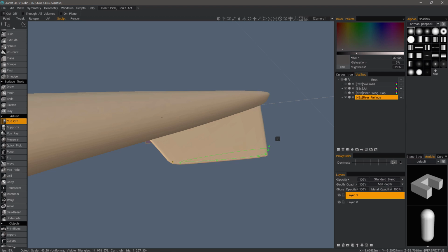And as you may know, you have different point types when using this curve. You have a standard spline that has curvature that runs through the point, and then you have a B-spline, which is quite a bit smoother because you can see it's weighted based on the angle. Let's hit Escape to drop the initial creation of the spline. You can cycle between them by right-clicking, as you can see. So I'll do that here. I'll right-click.